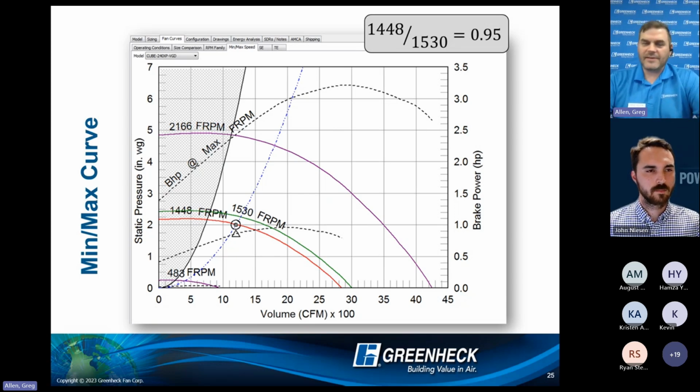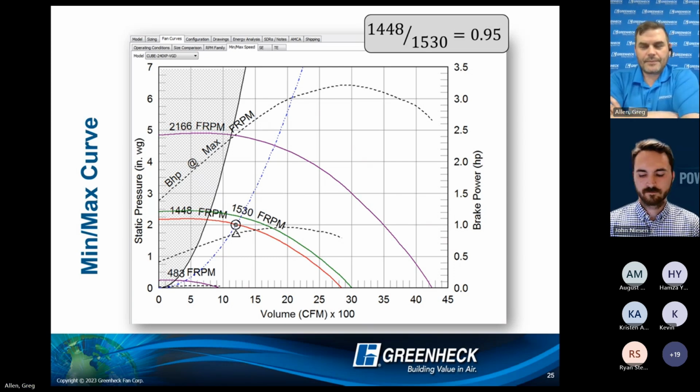Anything more than that, that HOA is an awesome little product. It acts like a remote dial. It acts like a 0 to 10. It does all these things, incorporates an aux contact, so I can make and break power for your damper actuator. You start integrating or interlocking your systems together, which really reduces your installation time and the cost of all the different parts going into it. The Hand-Off-Auto has a great reputation. Yeah, that's a problem solver for me.